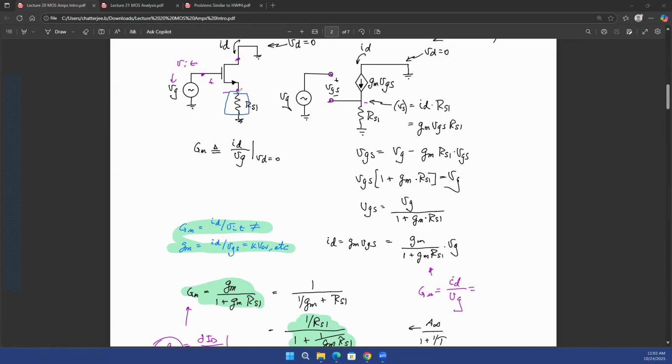Exactly. You already know the solution, and the solution was shown in your homework 3. The bypass capacitor. Let me already talk about the solution because you guys know about it. If you put a bypass capacitor over here, in terms of DC, the capacitor is open because the impedance of a capacitor is how much? 1 over j omega c. That is the impedance of the capacitor. So at DC, when omega is 0, the impedance is infinitely large. So the capacitor is an open circuit.